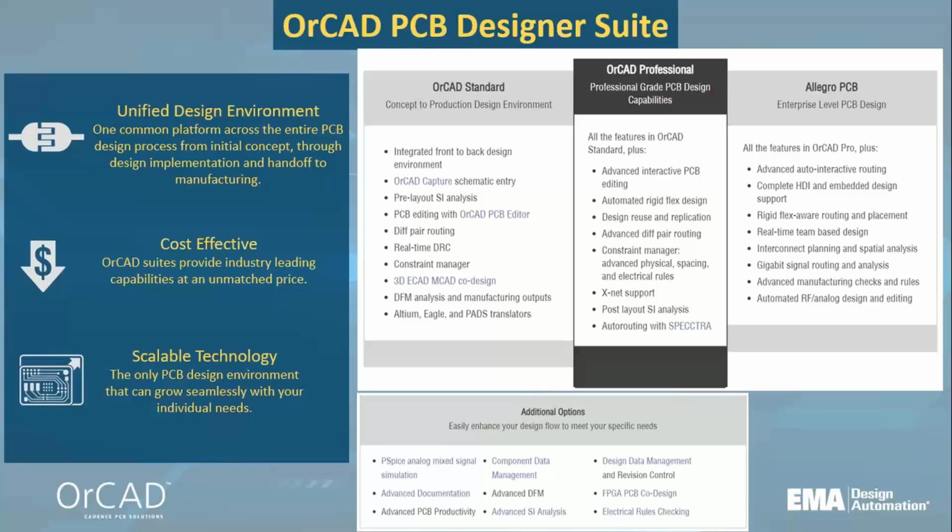When translating from PADS to OrCAD, are schematic and layout in sync? Like I said, yes, they are. You will be able to cross probe those. Is there a way to convert PADS board layout format into ASCII without PADS? There is no way. You'll have to have the PADS format.